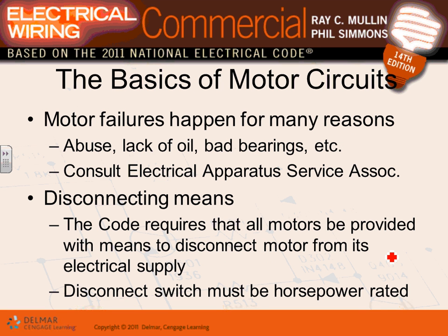So, summary, my friends: every time you are given an appliance or a motor or an appliance that has a motor in it, always ask yourself, do I have a disconnect inside of that machine? If not, then you have to install a disconnect for the motor, its machine, and its controller. A couple of things, guys, about motors.